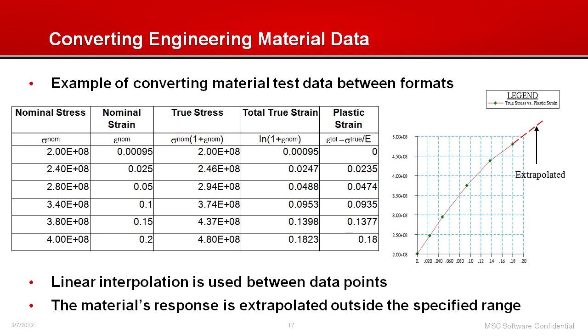So this is one format in which Nastran can take the stress-strain curve. And the other format is the true stress and the total true strain, and Patran can change the fields accordingly, and you could use that one as well. But for the demo, we will be using the true stress and the true plastic strain as part of the demonstration today.